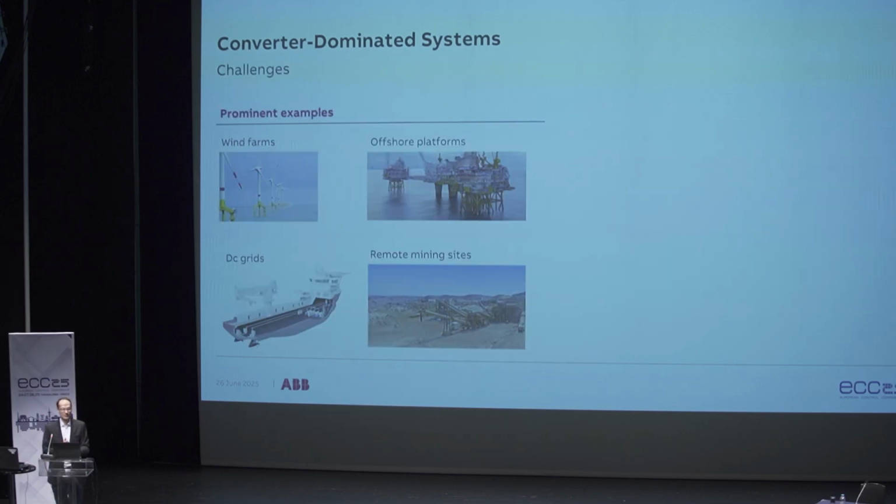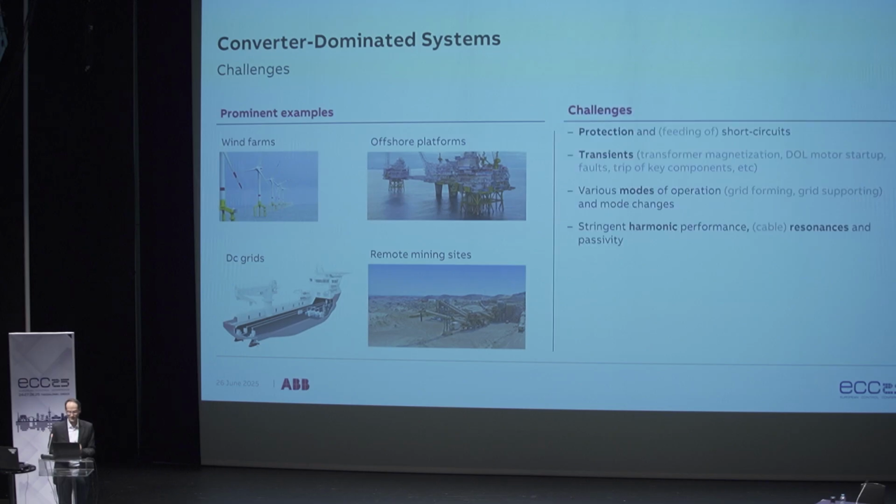Similar issues you can potentially have not just in wind farms, but also in any offshore isolated microgrids. Think of various loads, various generators that are now augmented by power converters. You can have it in DC grids on vessels or Navy, or on any remote site that is connected via a very weak link to the main grid and has lots of loads and lots of generating capacity online.